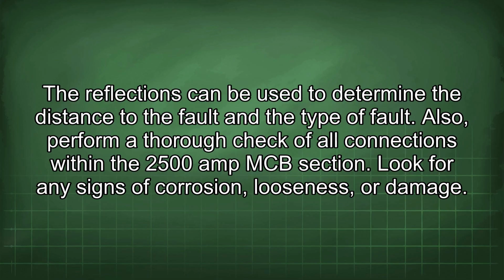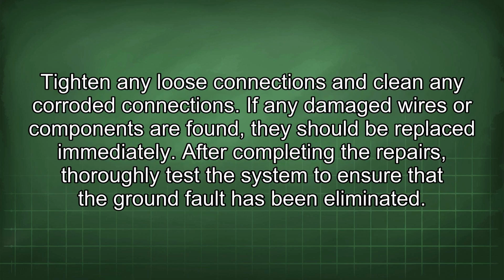Also, perform a thorough check of all connections within the 2500 amp MCB section. Look for any signs of corrosion, looseness, or damage. Tighten any loose connections and clean any corroded connections. If any damaged wires or components are found, they should be replaced immediately.